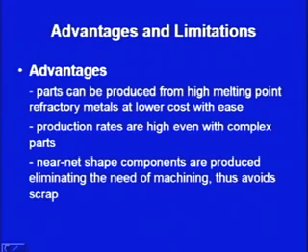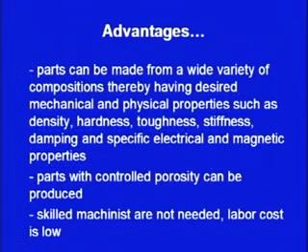Similarly, production rates are high even with complex parts. The part geometry may be complex, but the production rate is extremely high with powder metallurgy. Near net shape components are produced, eliminating the need for machining. Sometimes machining is not required, and we get the product in the final usable form. Thus, powder metallurgy avoids scrap and the process is economically justified.